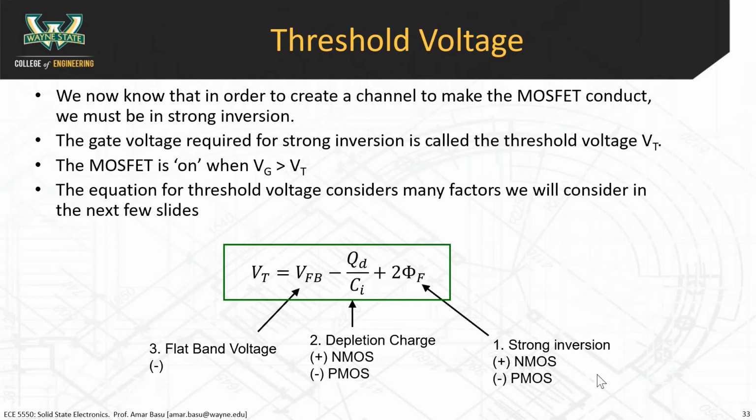So the threshold voltage, we touched on that last time. I want to finish that up before we get into the second order effects, and that's going to be most of today. So threshold voltage is a very important parameter in a MOSFET. If we think about a couple of practical things: if you're running your MOSFET off a 3.6 volt lithium ion rechargeable battery, the threshold voltages can't be more than 3.6 volts, right? That's one issue. Your threshold voltages can't be greater than the supply voltages in the system.